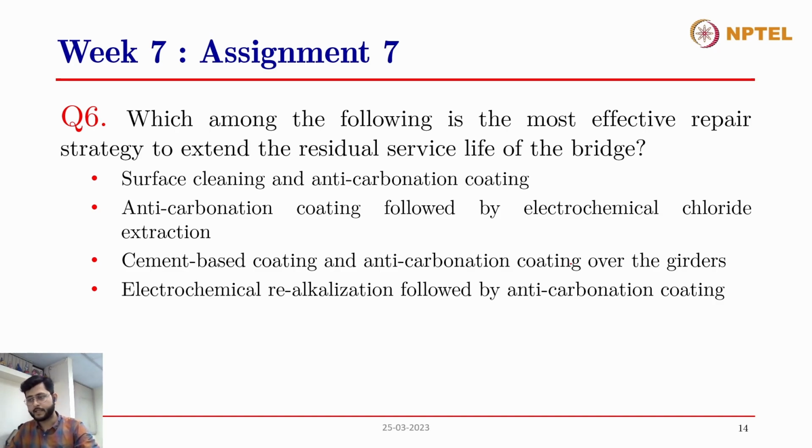The reserved alkalinity present around the rebar has been consumed by the carbonation process, and therefore the pH has gone down, and now the passivating film probably has been affected, and therefore the steel is more prone to corrosion now. So surface cleaning and only anti-carbonation coating won't work. Since the carbonation front has already reached the steel rebar location, we have to enhance the pH around that steel rebar location.